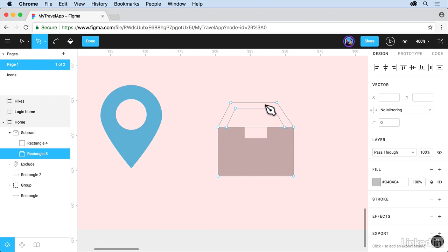There we go. Now, once we're done here, we could, if we want to, come to an individual anchor point and drag it or move it or do all kinds of things. You can even reshape or bend paths using the bend tool. I don't really want to do that, but we can also tell it what to fill with a color. So if you come up here, you'll see that we have the paint bucket tool. Click on that. It's going to use the same fill that the rest of the shape had.